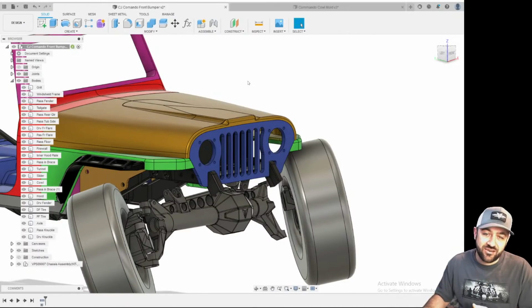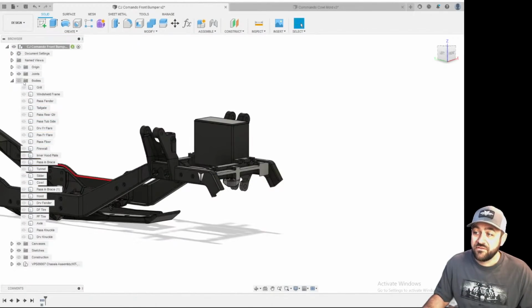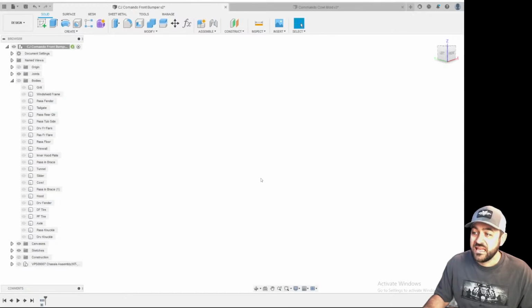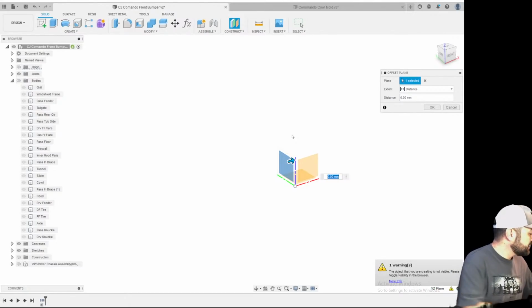So really, we need a starting point. Like I said previously, you're normally not going to have all of this info. So what I would suggest, even if you have none of this stuff and you don't have anything else to look at, is to create a new plane by grabbing the center, and then you need to measure the width of your frame rails.